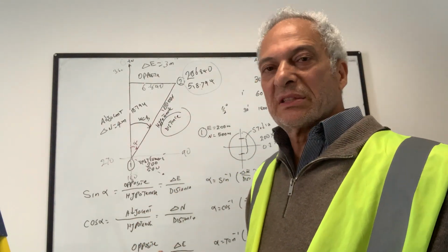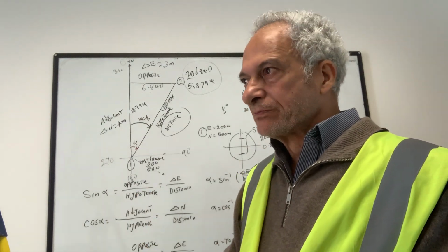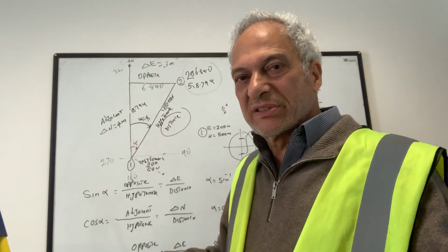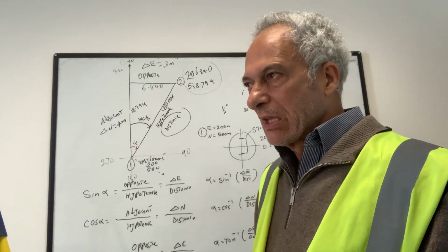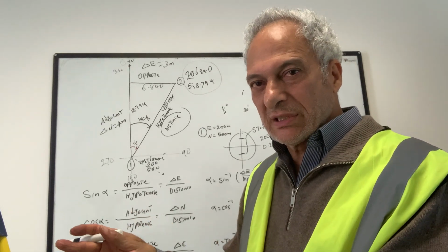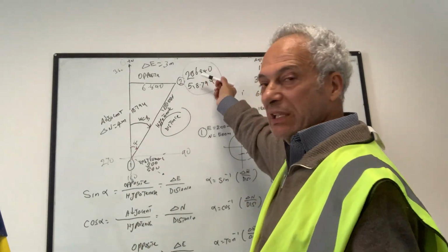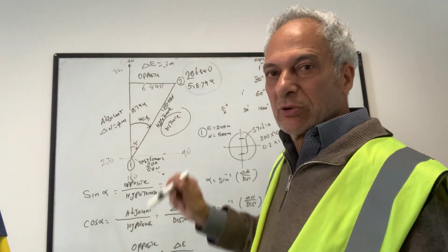And plus or minus 90 mil is good enough to mark 2 points on the ground with the given coordinates, and then use a tape, 3, 4, 5, to set it out more accurately. So if that plot of flats, for example, is anywhere within the land, it's fine. So you can use this to either set out or survey with given coordinates.